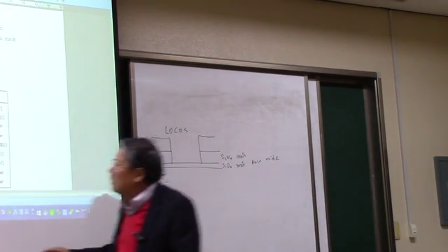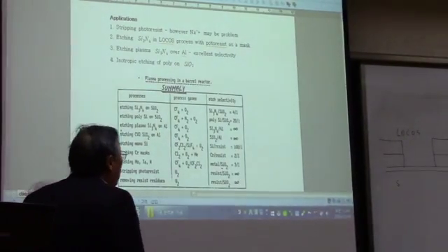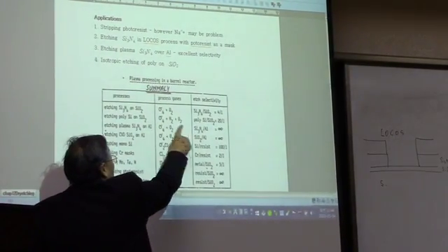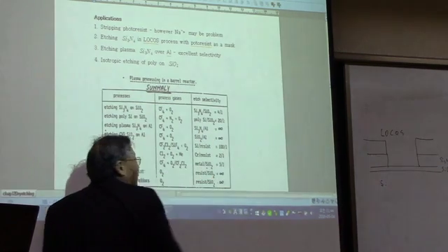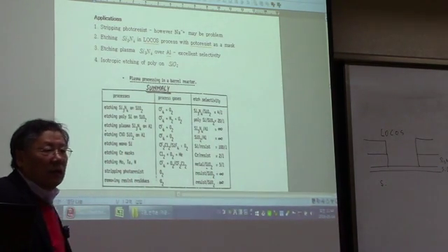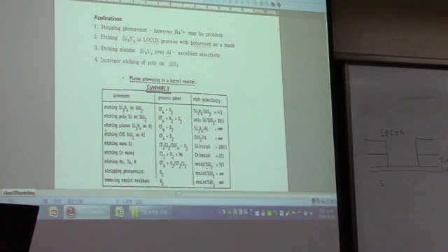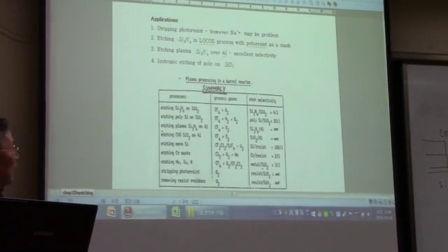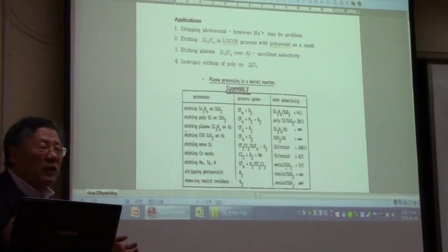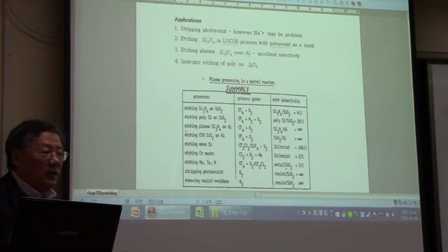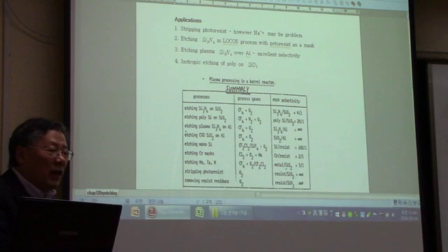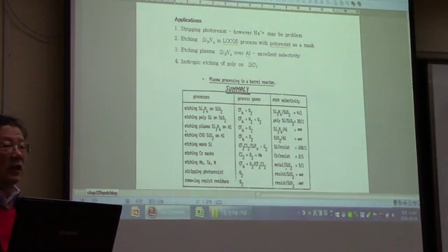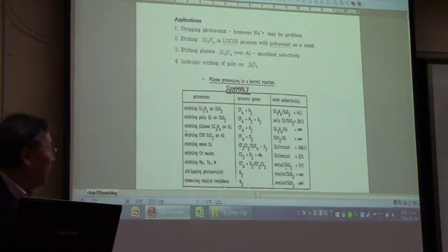But as you can see in the etched polysilicon and the silicon oxide, then we can use this plasma gas, and the selectivity is 20 to 1. So this means that we just put it in the chamber and then just wait until the polysilicon is entirely etched. Then the bottom layer, silicon oxide, is not going to be etched at all because the etch rate is 20 times slower.